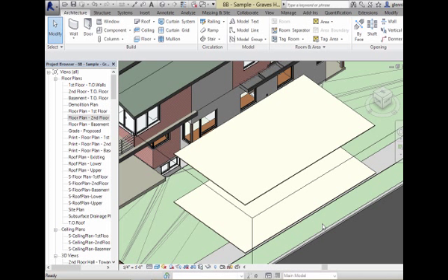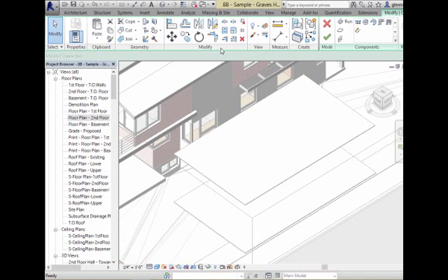So in your houses, 7-inch risers are okay, but it means you need more risers so the stair takes more room in the house. If you want to have an 8-inch riser, just to allow you the flexibility to do that, where you do that is when you choose the stair tool. I'll choose stair by component. That's kind of the easy way at first. You'll see that there's a stair where it has 7-inch max riser, 11-inch tread, and that's a type of stair. You'll see there's another one here that says 8-inch max riser. That's because in this model I already set it up this way. In your model I don't think it's set up this way by default.